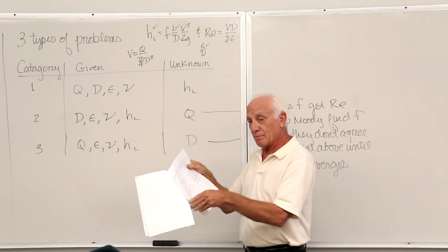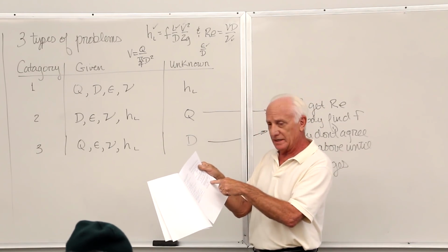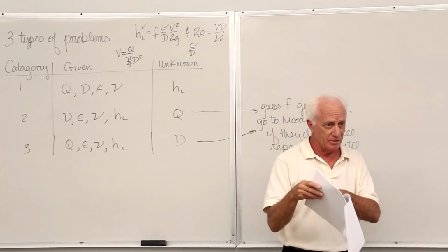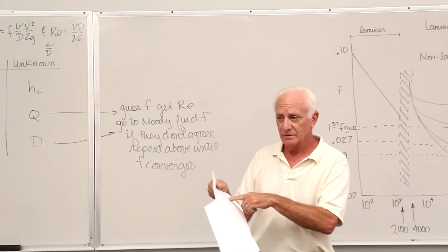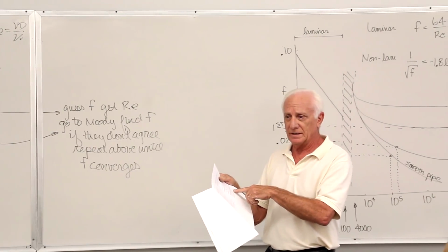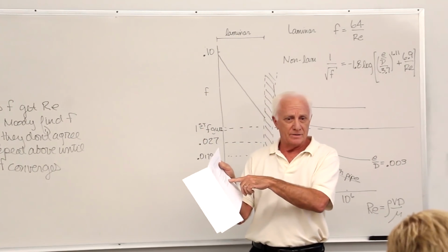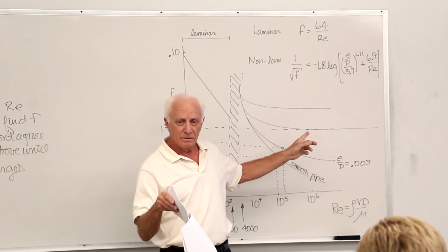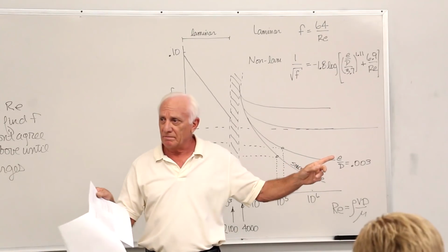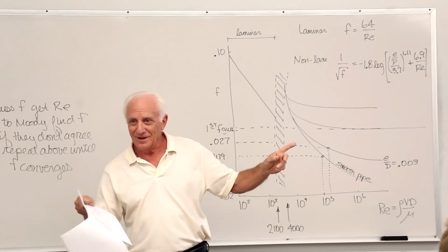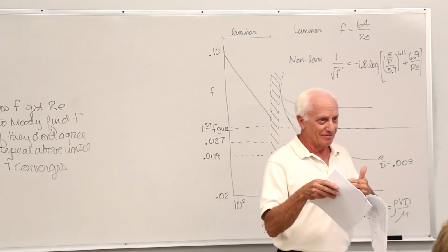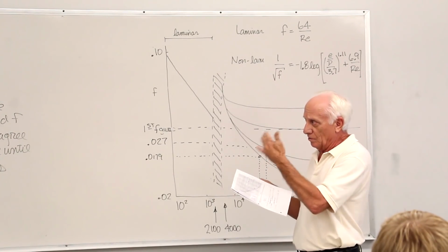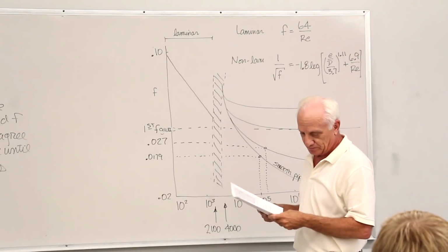Now put it in the approximate equation. Guess what they get? No iteration required. 3.9 compared to 4 centimeters. Close? Oh, of course it's close. Which one's right? Neither one's right. It says right there, the equations are approximate, and we know the Moody chart's only accurate to 10%. 10% of 4 is what? 0.4? Wow. So yeah, these guys are right on together. It gives you some confidence then in the equations, and that they'll work with the iterative procedure.